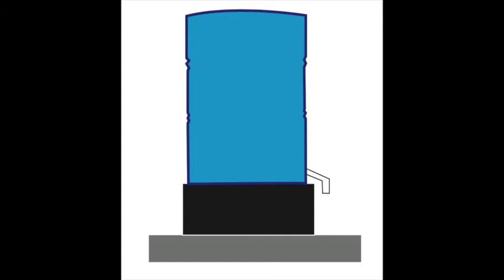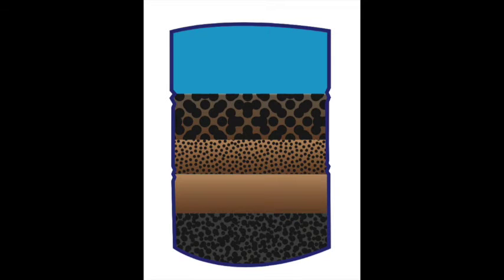The filters would be constructed around a 30-gallon steel barrel, 2/3 of which would contain filter media. Starting from the top down, we will have 8 gallons of gravel, 4 gallons of smaller gravel, 4 gallons of sand, and 4 gallons of activated carbon. The top 3 layers will be effective for removing larger particles, while the activated carbon will absorb the smaller compounds, the VOCs, the heavy metals, fine sediments, hydrogen sulfide, and the other taste and odor components.